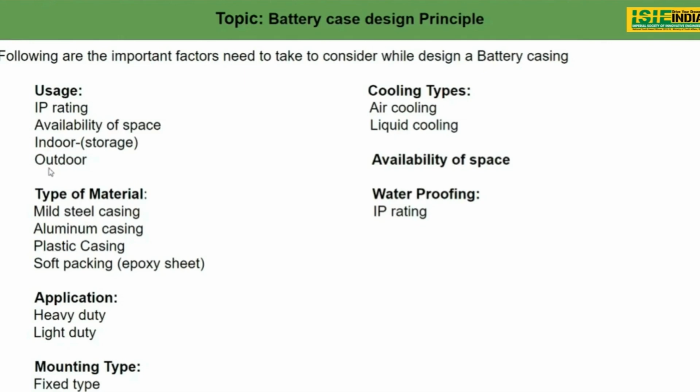So here, IP rating is important because a battery could be outdoor or indoor. Depending on that, we have to design the battery pack. Nowadays, due to a few fire incidents that happened in India, the government has strictly increased the rules on battery packs, which must have a certain IP rating. A battery should be water resistant and dust resistant, and it should not catch fire. So there are many regulations implemented by the government.